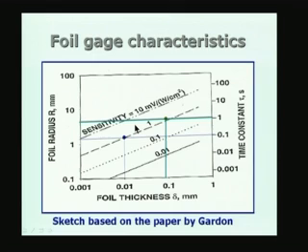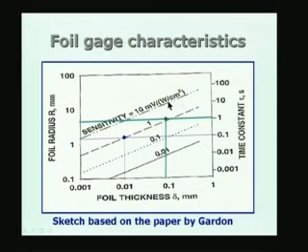Sensitivity is nothing but the reciprocal of the capital K. So, sensitivity is so many millivolts per watts per centimeter square. This is a more usual way of representing the sensitivity. Instead of microvolts and watts per meter squared, you use millivolts and watts per centimeter squared, and watts per centimeter squared will correspond to about 10 to the power 4 watts per square meter, and 1 millivolt will correspond to 10 to the power 3 microvolts.